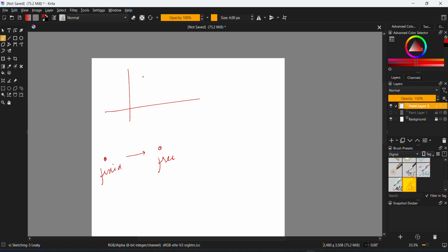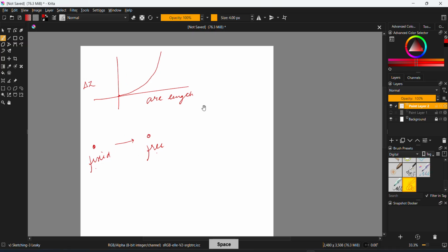the stress graph essentially is... Now if you look at the displacement graph, the fixed end is obviously fixed, so it's not going to move, but the displacement is going to increase somewhat exponentially. It's going to be a little linear, but slightly exponential. It's a higher order graph. That is my displacement in the z direction, and that is simply my arc length along the fixed point to the free point of the cantilever beam. This is for my displacement.